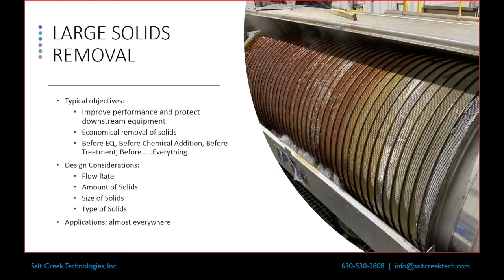So say during CIP, the first 10 minutes you have both sumps kick on, and for 20 minutes you have 500 gallons. That's the important thing you need to know for a screen. That's really important if you like having your wastewater treatment room be fairly clean. Otherwise, in that 10 minutes you're going to overwhelm the screen and you'll flood it out and end up with water all over the ground.